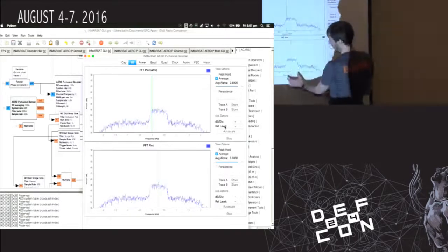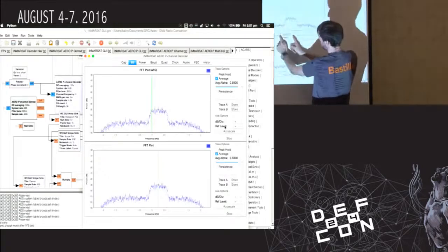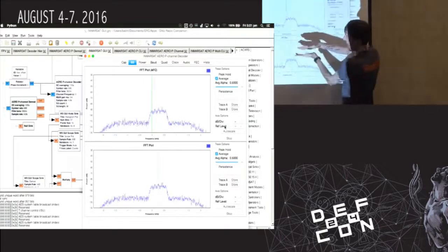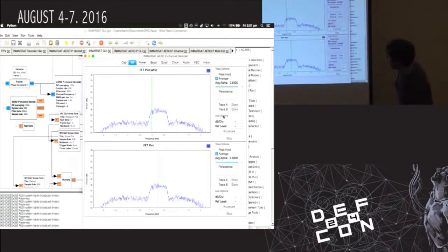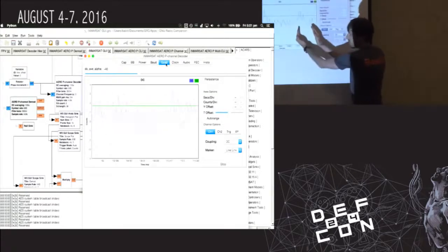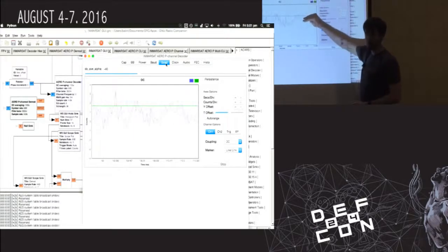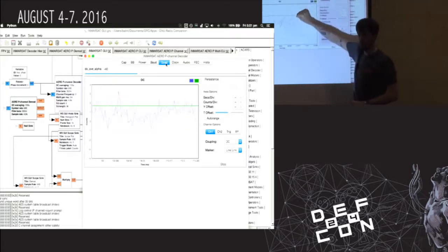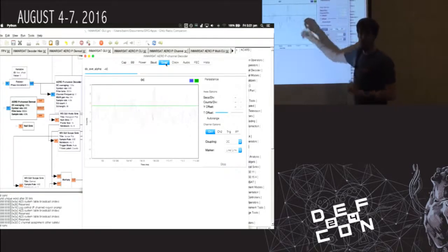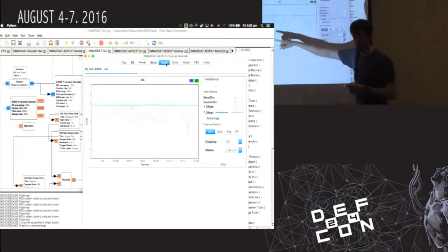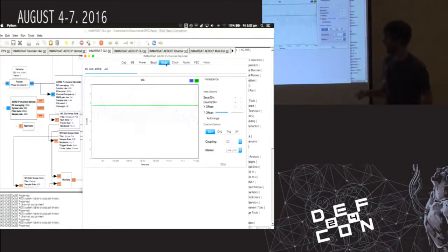This effectively moves your 1 and 0, which would nominally be at negative 300 and positive 300. Since we moved it, it adds a total offset to your output signal, which is what the green line is. Because we've moved it in frequency, we've got this DC component that's also moved with it after that long-term averaging. What's nice is that we can probe this DC value and convert it back into the frequency offset. It's linearly proportional to that frequency offset, so you probe it, do that little calculation, and get the DC offset back to Hertz.